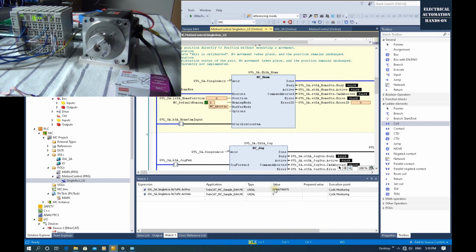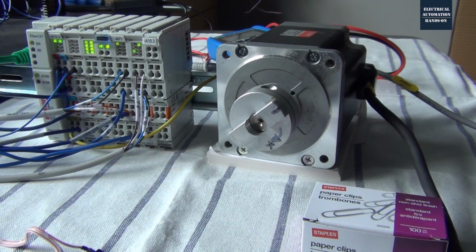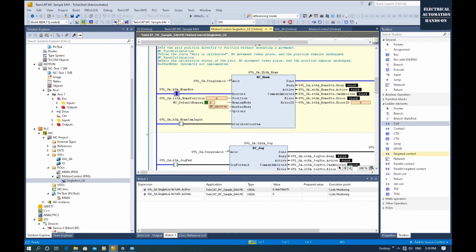So we can see, compared with the 0 mark, that means this position, the set value will not be that very consistent, because the falling edge, once the system got a falling edge, maybe that time the motion still slightly moving. So that's why every time this position won't be very accurate. But depends, some cases maybe this accuracy, that's accurate enough for you. After all, without 0 mark, incremental encoder has been widely used, right? So it depends on your application and the accuracy requirements. Okay, that is the home sequence.